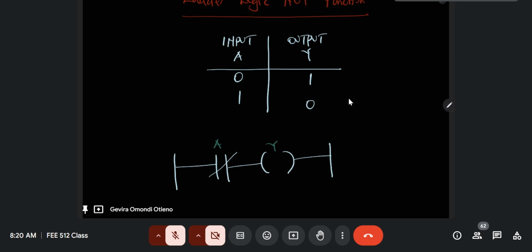that when it is not activated in its normal operation, it is allowing logic to pass through. But the moment you activate it, the moment you switch it on, then it opens, and then therefore it blocks logic from passing through. So in its normal state, it is always allowing. That's why we say it's normally closed contact, meaning in its normal operation, it allows logic to pass through it. But when you activate it, when you make it a logic 1 or a logic high, then it now closes. Sorry, it opens, because it's a normally closed contact. It opens, and therefore it blocks logic from passing through.